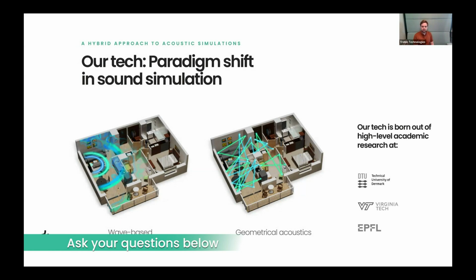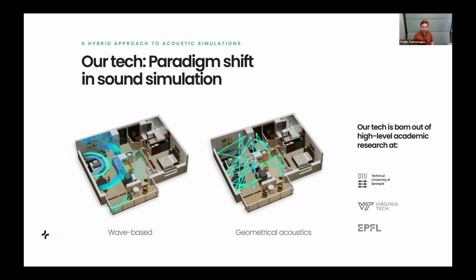Our technology is a hybrid room acoustic simulation setup where we have a wave-based finite element solver that handles the lower frequencies and a geometrical acoustic solver that takes care of the higher frequencies. This is all cloud-based due to the high computing power that we can harness using the cloud, which helps us run wave-based simulations at hitherto unknown speeds.